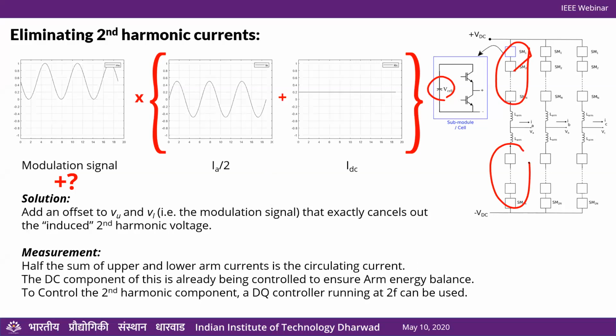And those 2n carriers are going to be spaced equally apart, so 2 pi is going to be divided by 2n. Now, when you want interleaved PWM operation, all we do is we assign the first carrier to this top module, next carrier to the next top module, third carrier here, fourth carrier here, and so on. That's the easiest way to do it.